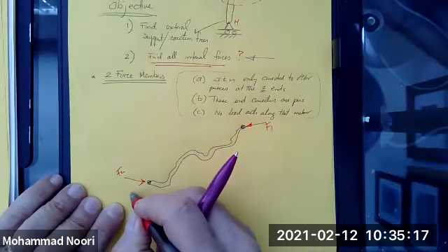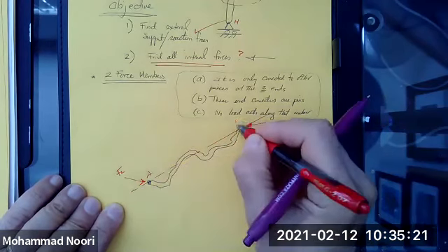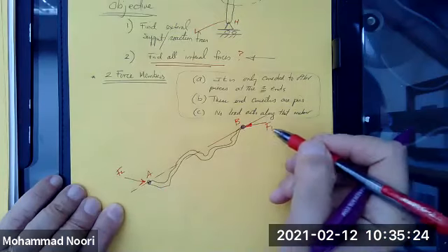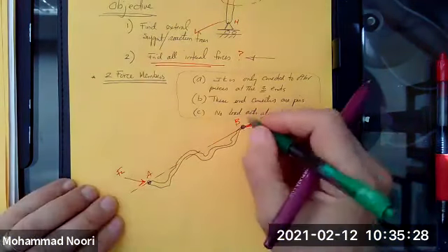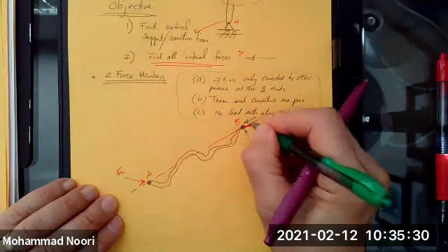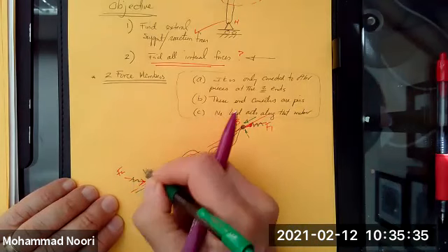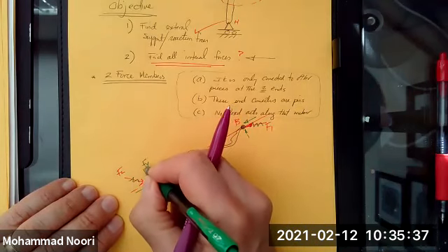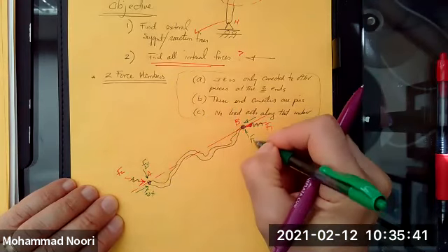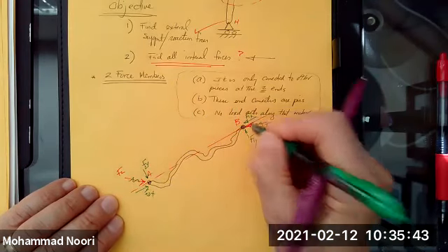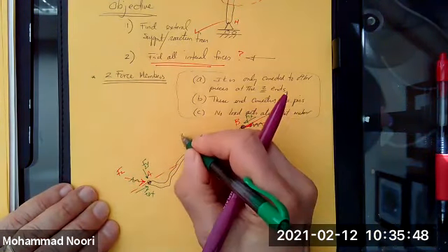So now let me connect the two ends along this line AB. To solve for these unknowns, I will resolve this force into its components, and this force into its components. So I'm going to call this F2y, F2x, F1y, F1x. All right? In other words, this is x, y.